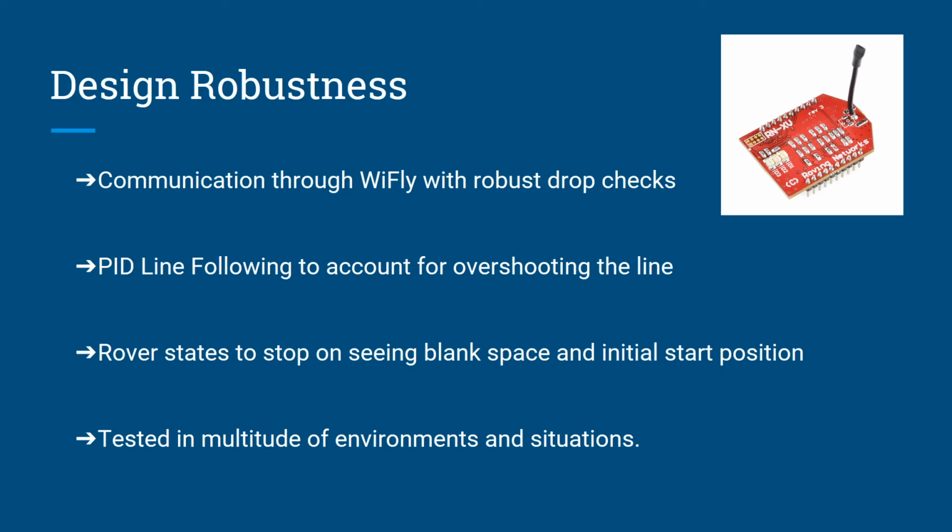For the servers, we made sure that these Wi-Fis would be connected as unique elements such that the server would be able to distinguish between the lead and follow rover and also be able to reconnect autonomously when signals were dropped, missing, or if packets were split, messed up, or just not coming. These were done and tested such that we could be certain that the rovers were receiving the correct messages and at the moments that we wanted them to.